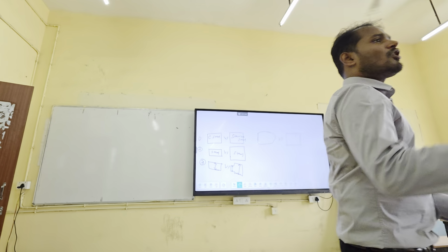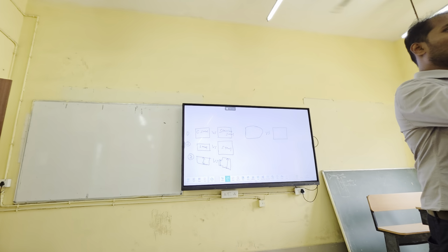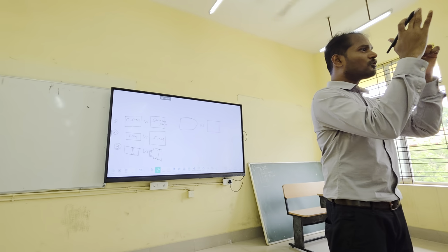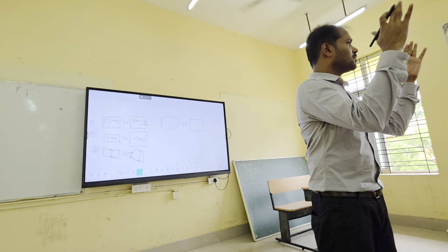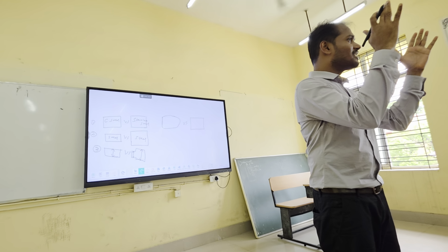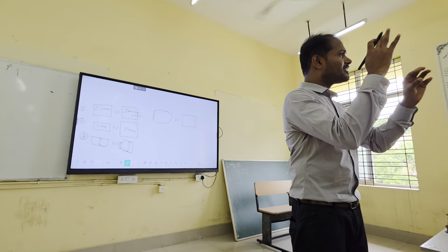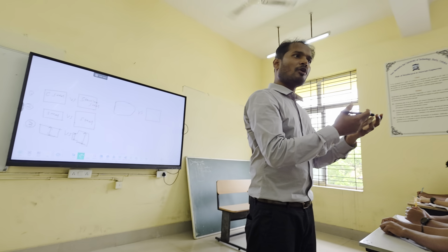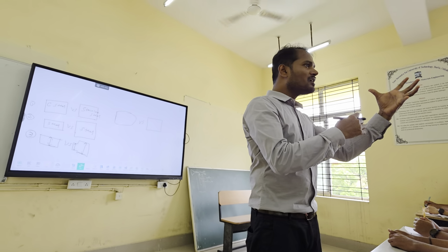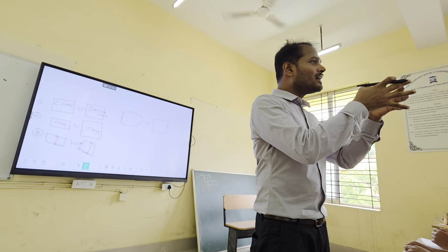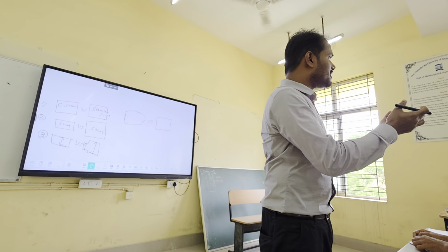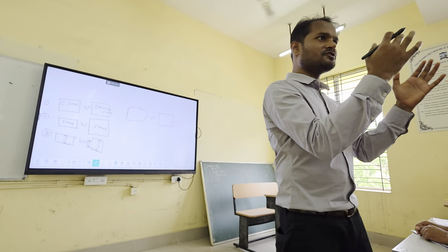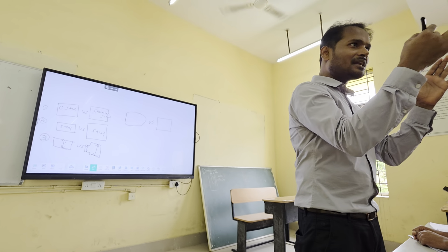See, suppose from here to here, electron wants to flow from here to here, right? In this distance. If it is a plain carbon steel, electron can easily flow like this, no issue. But if this is a stainless steel, apart from iron, lot of other alloying elements are there. So what will happen? Some strain will be there in the body. Why? Because some atoms will be bigger, some atoms will be smaller. So there will be a lattice strain, right? Localized lattice strain. Because of this localized lattice strain, when electron wants to flow in a straight line, it cannot flow.